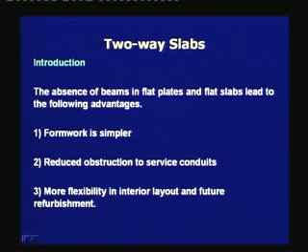The third advantage is more flexibility in interior layout and future refurbishment. That means, once the building has been made, then the client has his or her own choice to lay out the interior of the space. Now, this is more convenient if the building is made up of flat slabs or flat plates.